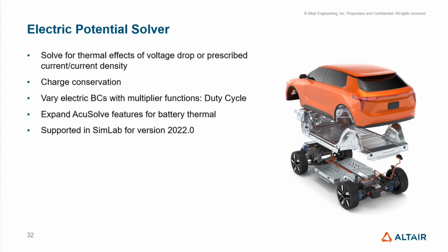So with AcuSolve's electric potential solver, the thermal effects of electrical inputs can be simulated based on the solution of the conservation of charge. Duty cycles can be simulated through multiplier functions on the electrical inputs. And this feature is available in the 2022 version of SimLab.